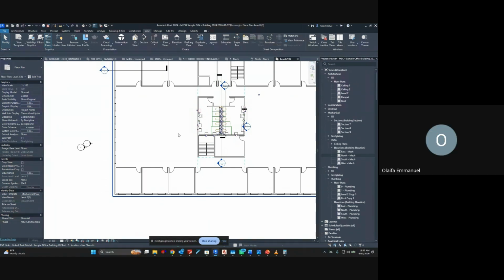Okay, when you use a ceiling plan, you don't have to increase elevation. It gets hosted on the ceiling directly. Yeah, good, that's very good. When you are using a ceiling plan, the element you are hosting goes on the ceiling. You don't have to worry about the elevation. It's hosted directly to the ceiling. That's if the architect has actually given you a ceiling. But with this architect, there's no ceiling there.